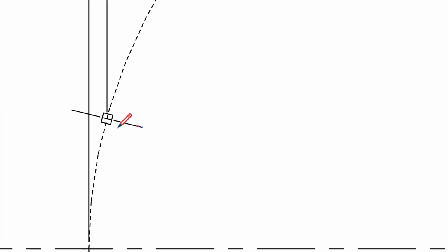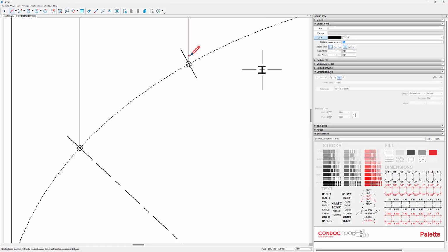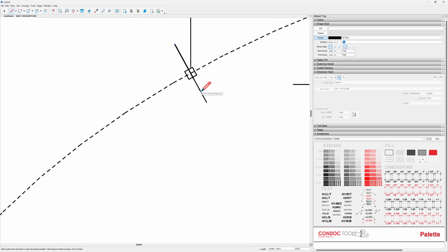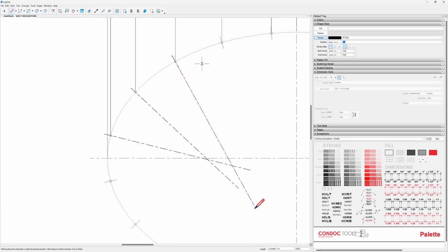All you have to do is draw this line in, and then you can continue it on like this. I'm just gonna extend past. So if I trace this line here and then continue on beyond it like that, well, let me just make sure. If I hover on this, it doesn't give me that inference. But if I turn that into layout geometry, you can see that now I get that magenta inference. So then I can project these out like that.